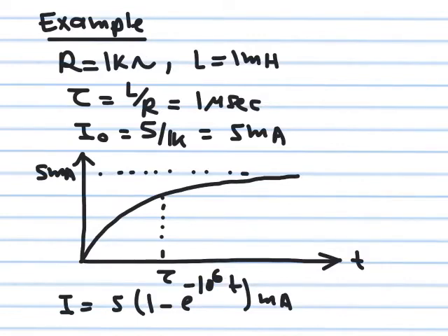So it's about 1/3, a little bit more than 1/3. So this means that at time tau, the current has risen to 5 multiplying 1 minus about 0.35. Maybe it goes up to 0.66 something of its maximum value. So it will go up to 3 milliamps or something.